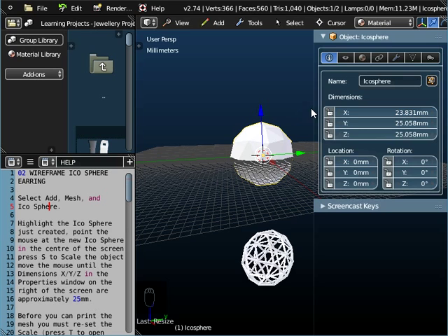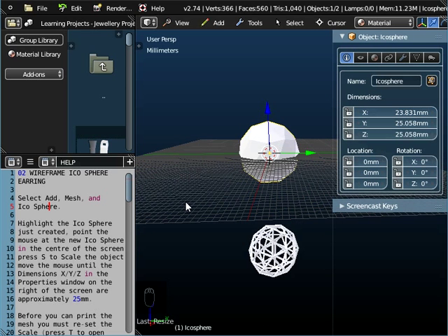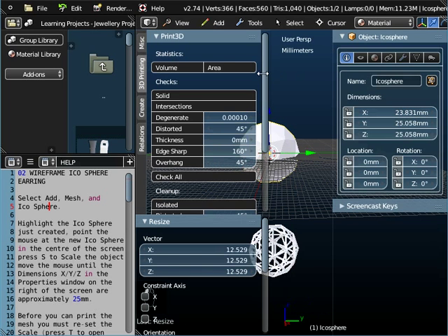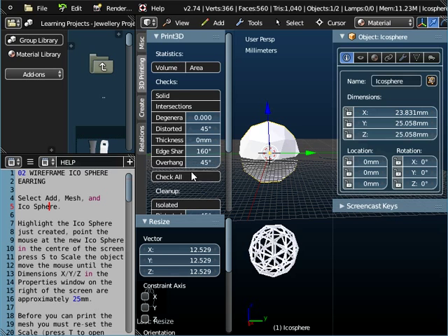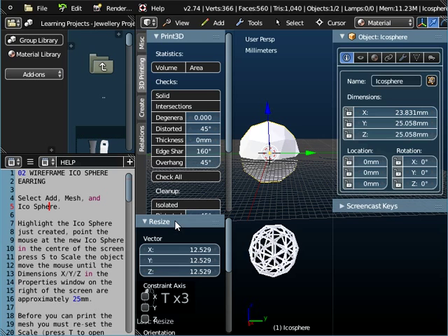So we've resized it. Now, one of the things to always remember in FluidDesigner, when you resize objects, if you're going to do printing, which is what we're interested in, you always need to open up the toolbox. I press the plus sign at the top. You can press the T on the keyboard, that will open and close the toolbox, or you can click on the plus sign up here.